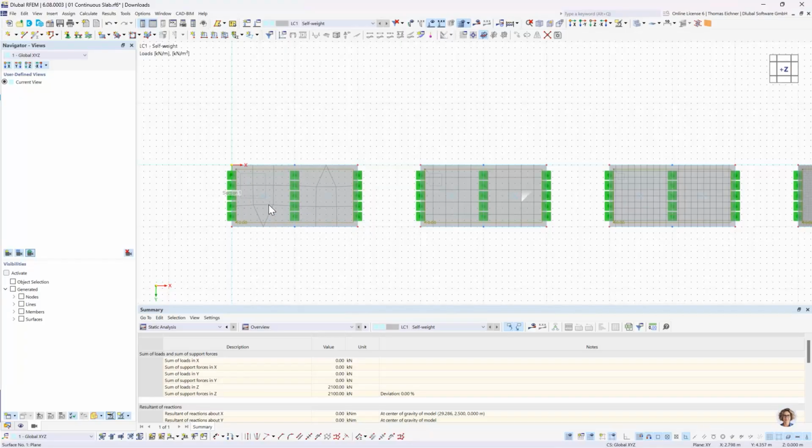And we even have a triangular element here, which is also never perfect, since it's just better to have a uniformly distributed rectangular finite element mesh. Sometimes it's not possible to avoid those triangular shapes, but if possible, you should try to avoid them.